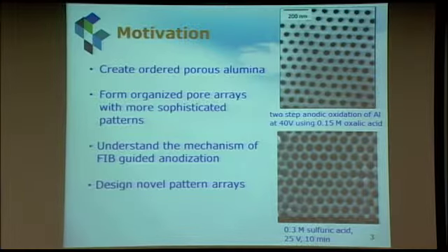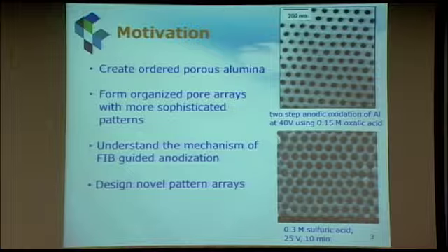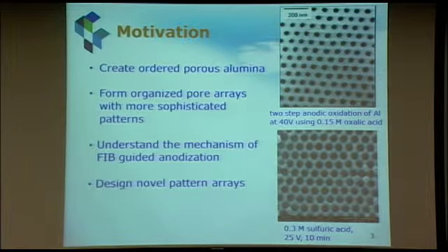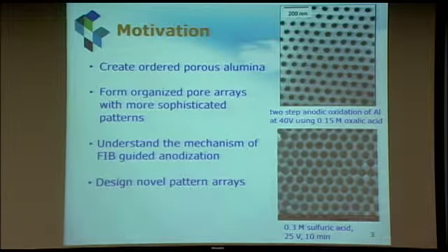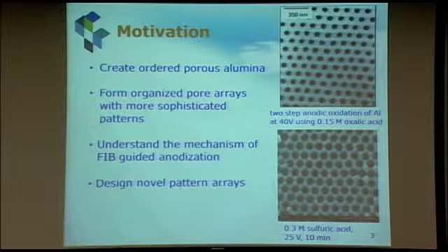And so when I started this work, I said, okay, can we do something different? Even though it's hexagonal, you only get one kind of arrangement. Another issue is these processing windows are very, very narrow. You've got to be very careful. If the material has certain defects or the processing condition changes, you get a very random arrangement of pores and very different sizes or even different shapes of pores. To get this kind of arrangement, they are mostly confined in very small areas and oftentimes very hard to do.